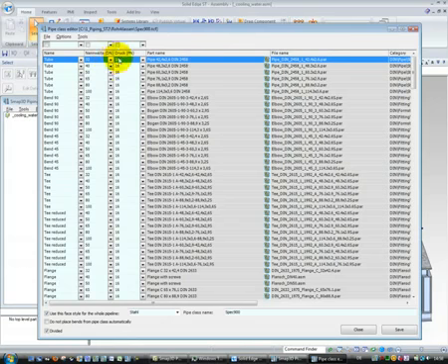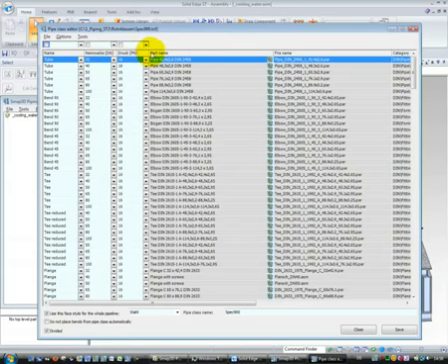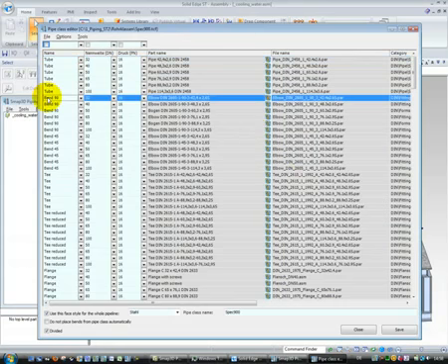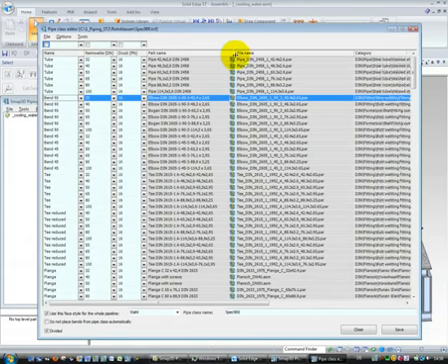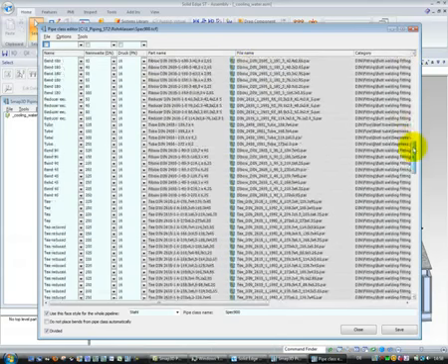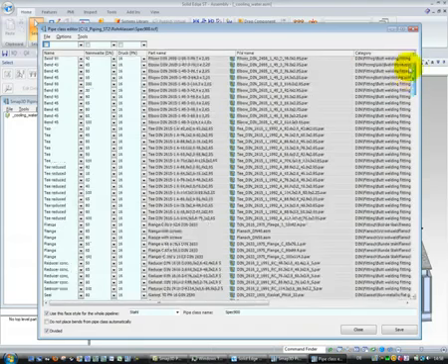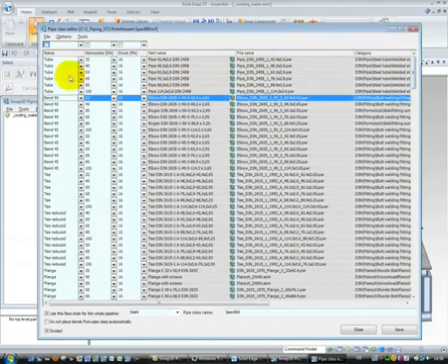In this open pipe class we see a lot of rows and several columns which are filled with values. Every row does represent one component which should be used automatically by the piping application to create 3D pipelines. Every row does represent one specific component. And here we divide the rows which are colored with a light green.